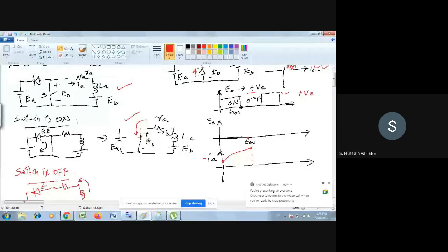Once you got this voltage zero, I have drawn the waveform here. Zero voltage I have drawn here. In that case, what is the current flowing? That is the question now. As the switch is closed here, the current will get reversed like this. The reference direction I have taken is from left side to right side, but the actual current is flowing from right side to left side. That's the reason I am drawing the waveform of minus IA, not IA. The minus IA waveform rises in the negative direction in an exponential way for as long as T on is there.